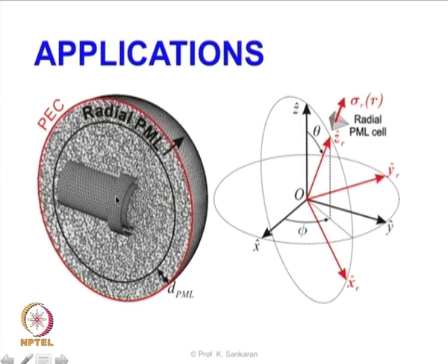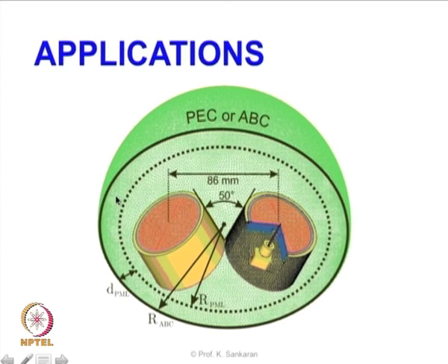This example is very simple, but we are going to talk about a case here with a very complicated geometry, because we have totally 2 pairs of 26 windings, and these windings are 0.25 mm in thickness. So it is very fine windings, and these are Archimedean spiral antennas. What we are interested in here is finding out the coupling between 2 spiral antennas. One antenna will be a radiating antenna, the other will be the reception antenna. We are interested in seeing what the coupling between these 2 antennas is.